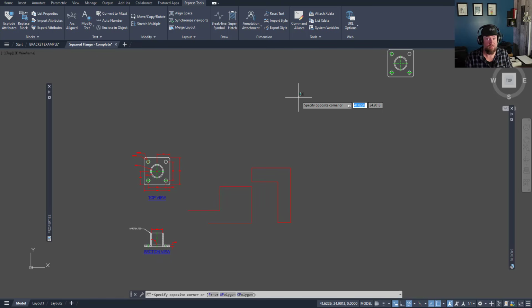Every drawing you create will be based on that template, and it's going to have these same scales, these same layers, the same colors, the same title blocks. This is hugely important for standards and drawing production so that every drawing you produce at least has the same starting point so that it can look similar. It's going to have those same text sizes and fonts, the same title block, the same logos. Everything that you've customized and created and inserted into your template is going to be brought into that new drawing. You no longer need to copy an old drawing to start a new one or insert things from previous projects. Just starting with that template with everything in it is going to be a huge time saver.